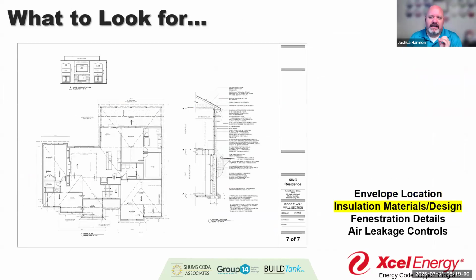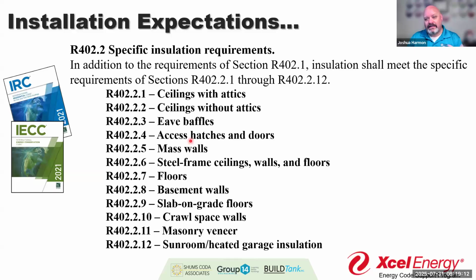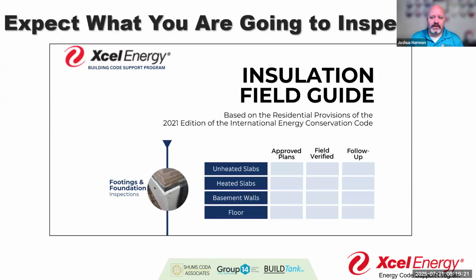But when we start getting into the question of insulation materials, that's when REScheck really comes out. When we start thinking about those lists of tables that we find in section 402 and those specific insulation expectations, we know that there is a variety of things that we're looking for, both in the plans and when we go out and do our inspections. I think we talked about this to a degree when we got together on the 17th and talked about the overview of insulation. This field guide should be available online. I'm hoping it's available there. If it's not, please reach out to me and we can send you the installation or inspection field guide that we've put together.